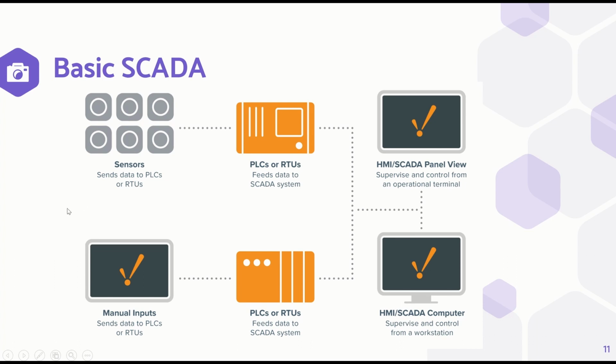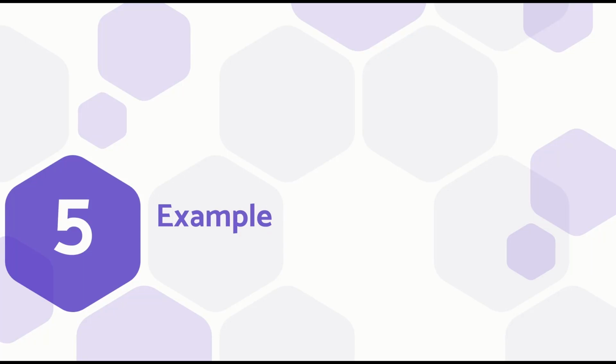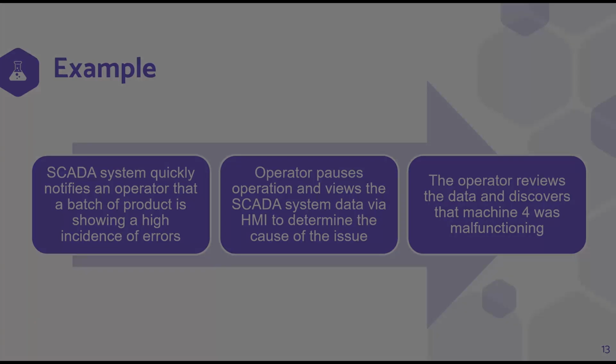view. So here first, the basic SCADA architecture begins with programmable logic controllers, PLCs, or remote terminal units, RTUs. PLC or RTU are microcomputers that communicate with an array of objects such as factory machines, HMI, sensors and end devices, then route the information and objects to the computer through the SCADA software. SCADA software processes, distributes and displays the data, helping the operator and other employees to analyze the data and make important decisions. So let us see some of the examples.